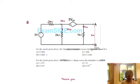Okay, so in this manner, I hope through the slightly different problems that we have been addressing, you have got a feel for how easy the dependent source problems are, especially because of the dependence. The dependence reduces the number of variables, so it's easy to do. The three important things to remember: when you are looking at the problem, go straight for the dependent source, and be focused on where the dependence is. That's point number 1.